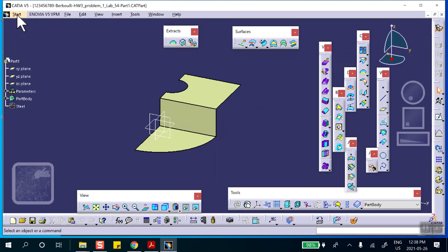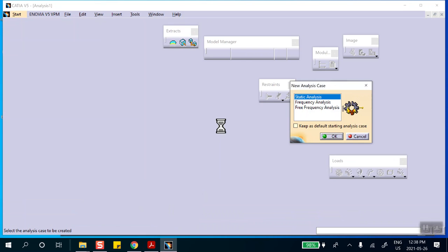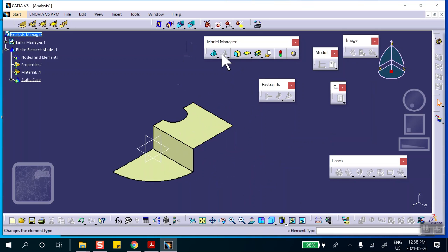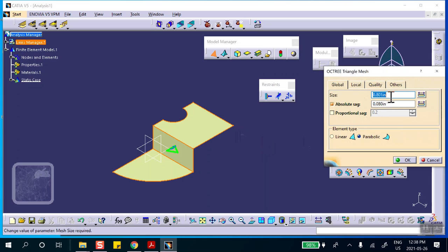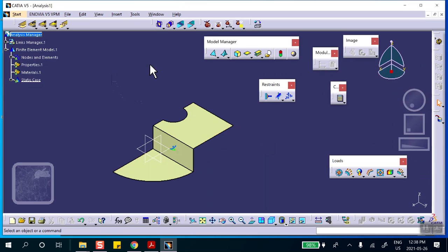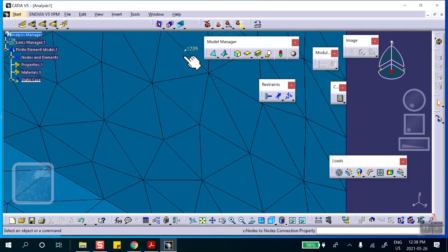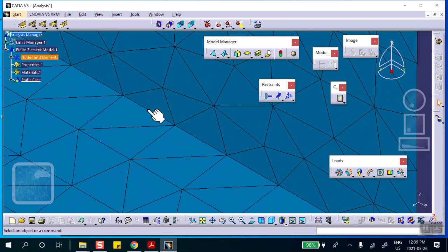And we go to generative structure analysis. Okay. Let me change the rendering here. Okay, very good. We're going to measure the shell elements. Make it smaller. 0.3. We say okay. We can look at your mesh if you want. And because of what we did with joining, if you look at the element node numbers on the two sides, on this side and on that side, we have the same. See, 51 on the edge, 52 on the edge, on both sides.